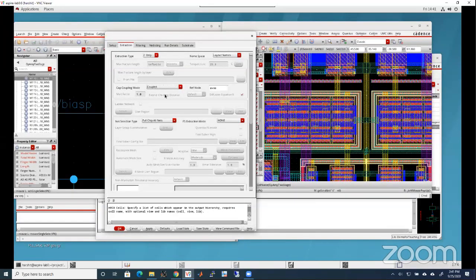Now, why did they give these three options? Because precision simulation is best, right? The coupled netlist will be much bigger, so simulation time will be larger. So depending on what aspect of the circuit you are looking at, please choose your extraction deck appropriately. Now, what are the different things that we have to look at? I hope you wrote down all these cases.